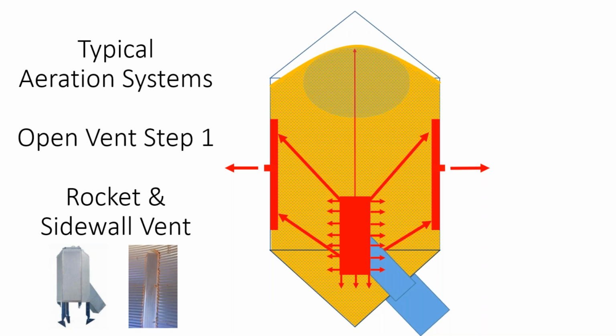So the way that this works is you start with step 1, and these sidewall vents are open. You'll start up and the lion's share of your air is injected in a very optimum, sideways direction. It is going to try and travel the easiest path, which is horizontal. And as it hits these sidewall vents, it's going to exit.